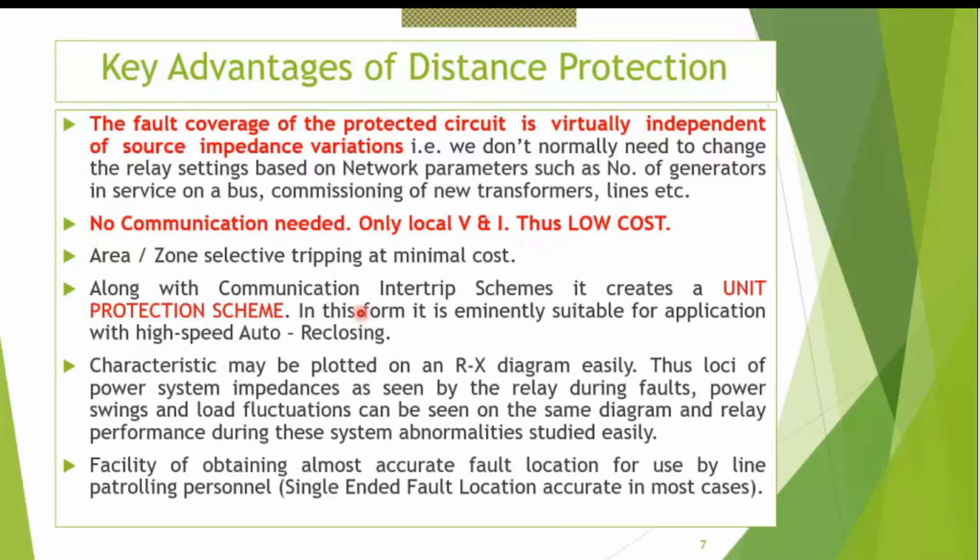So in this form, it is eminently suitable for application with high speed auto reclose. What do we need in an auto reclose? We need the fault to be in the line section. If the fault is outside the line section and we reclose, then we are not doing the right thing. We are creating problems. It is in another section.